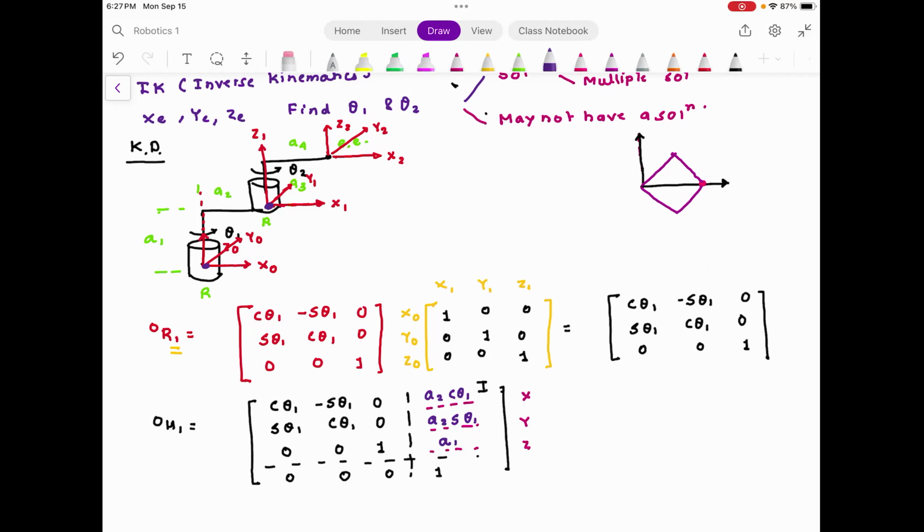I would explain this one more time, but it's extremely important. Homogeneous transformation is one of the most fundamental matrices that you need to solve the forward kinematics problem. Homogeneous transformation is a 4 by 4 matrix that encodes the orientation and the relative displacement or relative distance between the previous frame and the next frame, in the coordinate system associated with the previous frame.